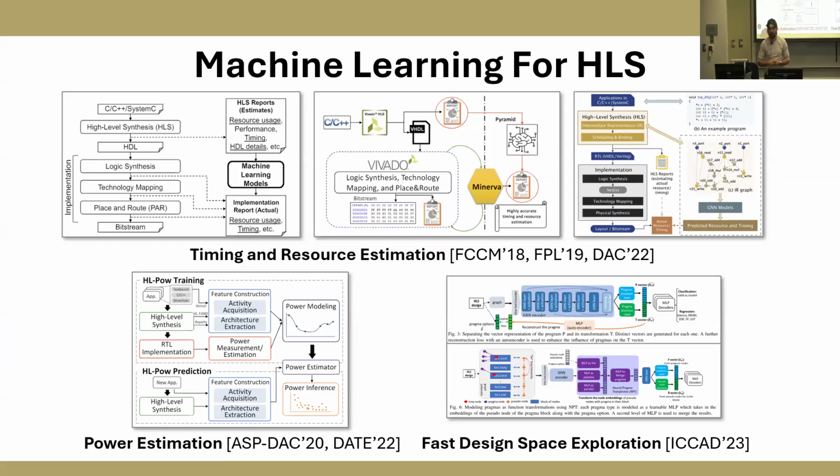This is pointing out machine learning for HLS. Essentially you write your little HLS program, and the synthesis tool will spit out the implemented version. It'll tell you the latency in terms of clock cycles or nanoseconds, and how many resources you used, like how many LUTs in the FPGA, how many pieces of memory, and so forth. One very active area of research is, given the program you wrote, without running the actual tool, can you predict those things? Here's the code, predict the latency of the kernel, or predict how many flip flops and LUTs I'm going to use.